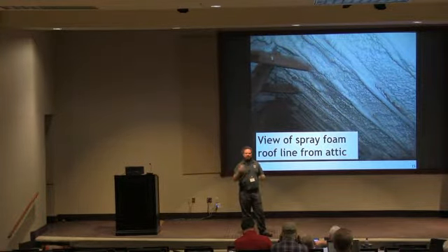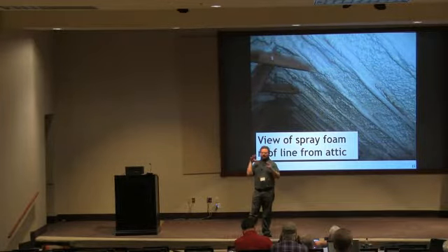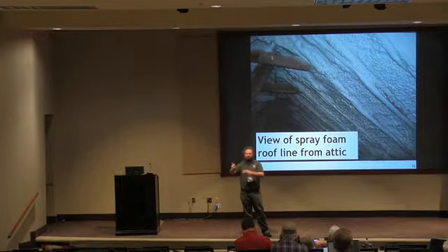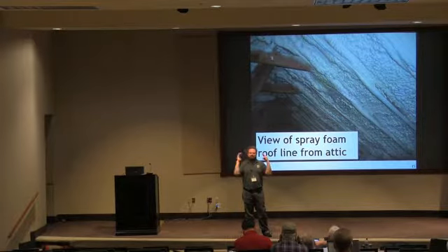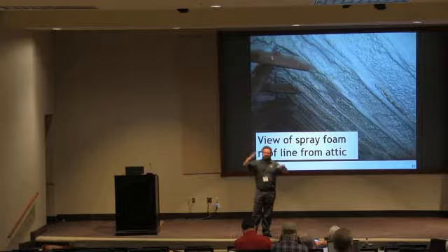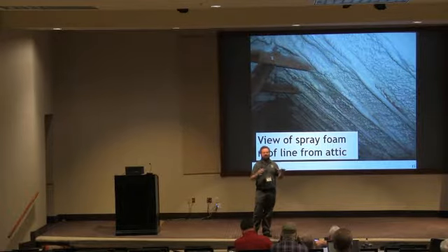It's interesting because radiant heat transfer is surface to surface, unlike conduction, which flows through a solid and will find the thermal bridge, the pathway of least resistance. Radiant heat transfer is about surface area. So a radiant barrier can be installed as a retrofit and work pretty well, and even if you don't have 100% coverage, you still get the benefit for whatever percentage gets covered. So a product like that is most likely a retrofit radiant barrier someone did.